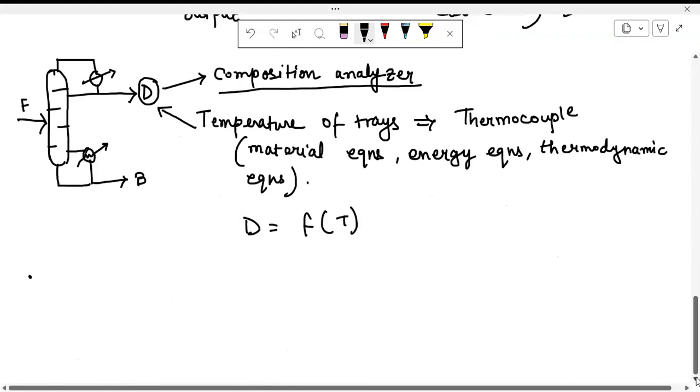But suppose we are able to measure the disturbances, say that the temperature variable from an incoming stream is the major disturbance. We can measure that using a thermocouple. In that case, we will record that measurement and we can take some remedial action.